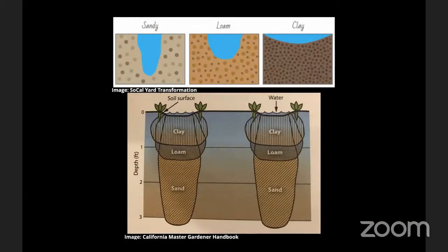What you generally need is called a check valve. There are different types of check valves, different configurations. It gets a little bit beyond what we can get into now, but what I would recommend is take a few pictures of your situation, your valve, your slope on your phone, go to the local landscape supply store and say, I want to prevent backflow in this situation. I heard that I probably need to look into some sort of check valve that's going to be installed along the line to prevent the water from flowing back down. What would you recommend?